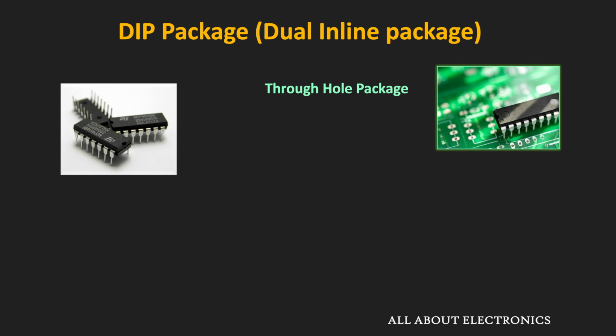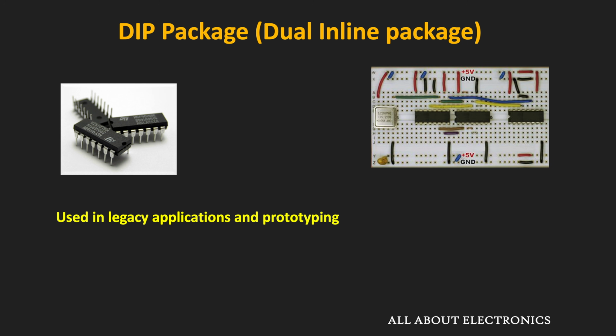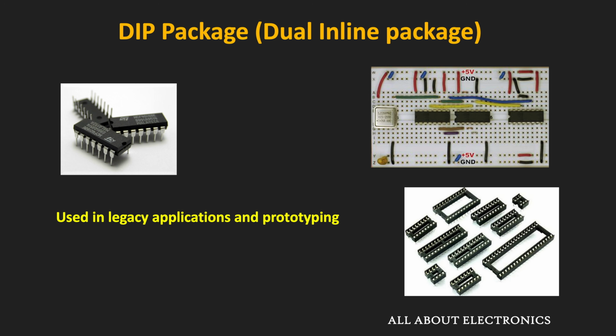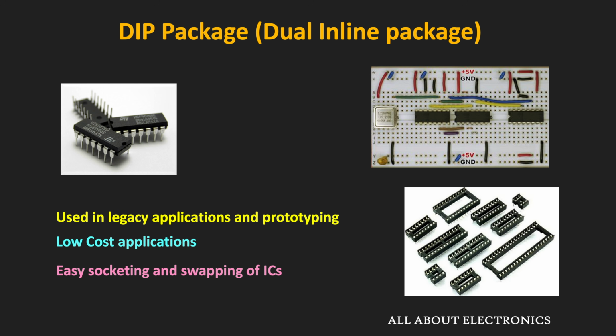Nowadays, many ICs do not support this DIP package, but it is still used in some legacy applications and commonly used for fast prototyping, specifically when we want to do fast prototyping using a breadboard. Moreover, this package is also used in education as well as training kits, because with this IC package, using readily available sockets, it is possible to swap the ICs. This package is also preferred in low-cost applications.